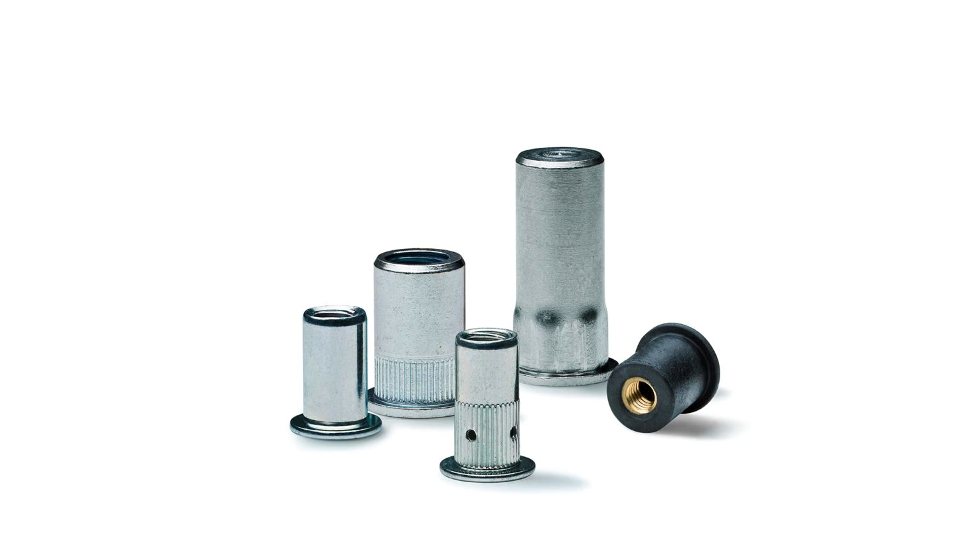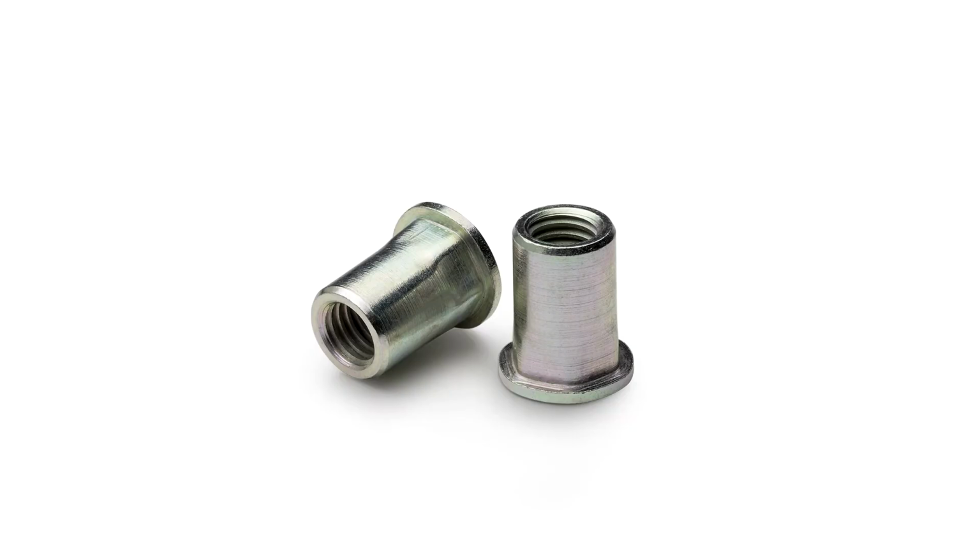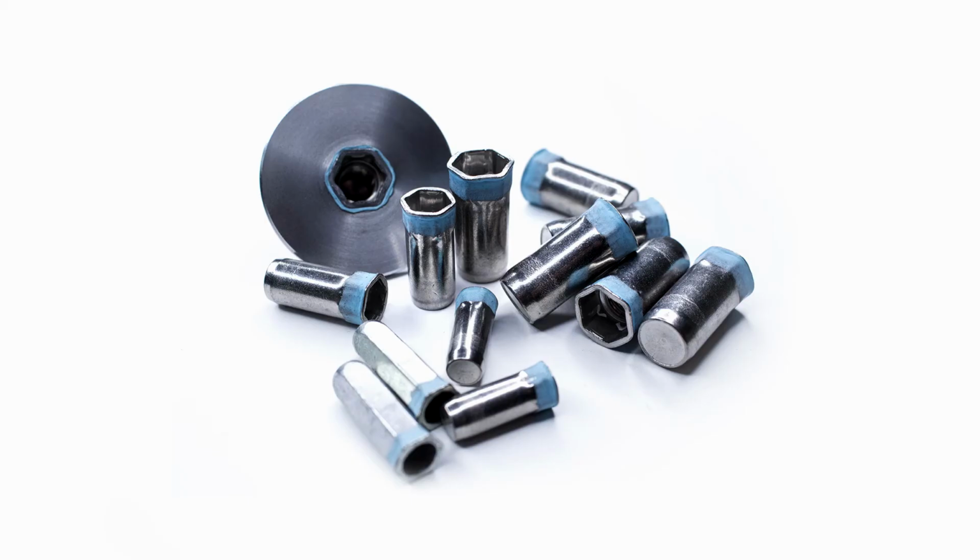There are many different types of blind rivet nuts on the market with different functions and advantages. The main types are standard rivet nuts with an open end. Or if you want to avoid water or gas leakage up to IP67, IP68, we offer standard blind rivet nuts with a closed end with a sealing under the head.